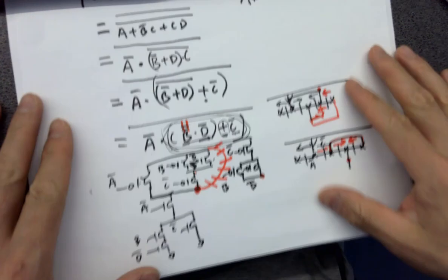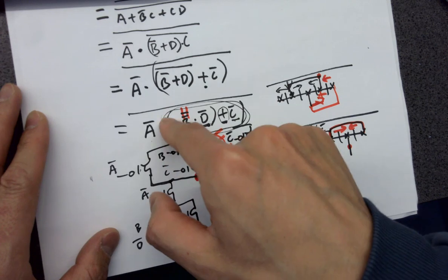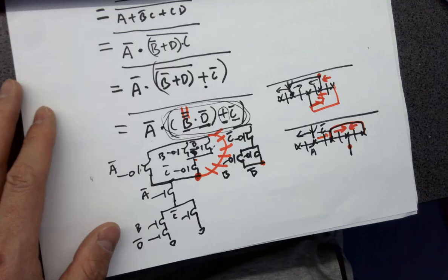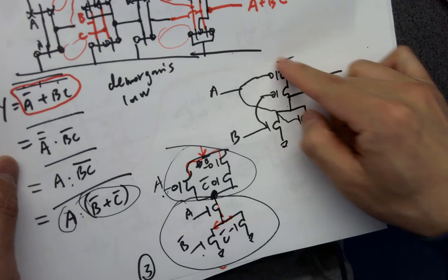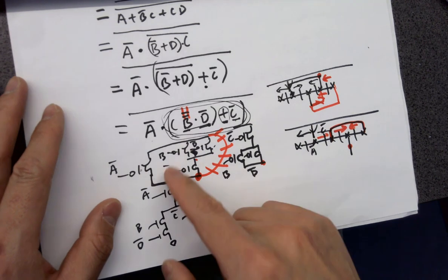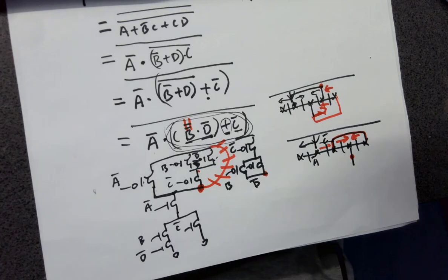So we can directly draw the circuit like this. Eventually, it will be serving that logic expression. Since we have the conclusion over here already, we know that if we draw a circuit like this, it's going to be inverted eventually. Okay, so that is why we are trying to get a bar on the top first. That's just a method. Okay, what's that?